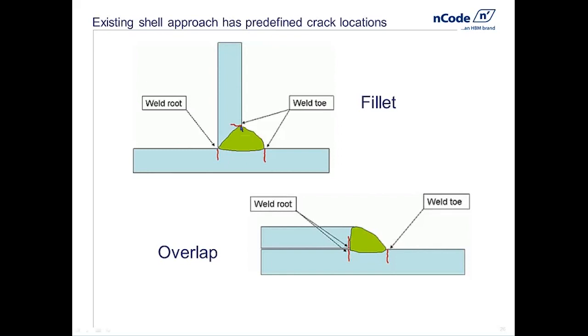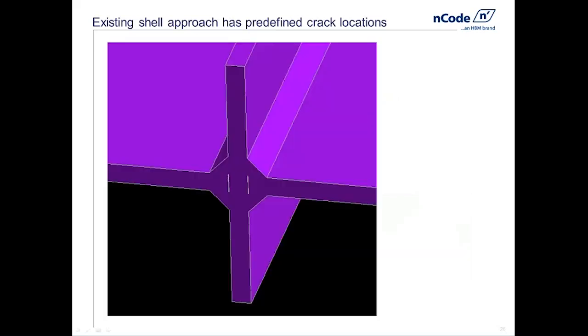In the solid technique, the user defines the direction to do the stress linearization, and the stress linearization basically defines the failure path. So here, what we're looking at is a weld, and the horizontal plates are two plates that are basically loaded in tension. These are two separate plates, and the connection between the two plates now is a common weld with a small vertical riser plate. If one looks closely here, you'll see that the weld only represents a portion of the connection, and the base of the horizontal plate is not physically connected to the vertical plate at all. So this is a partial penetration weld.